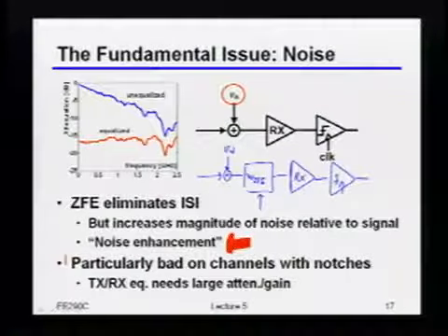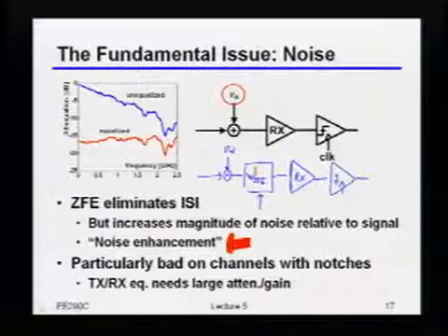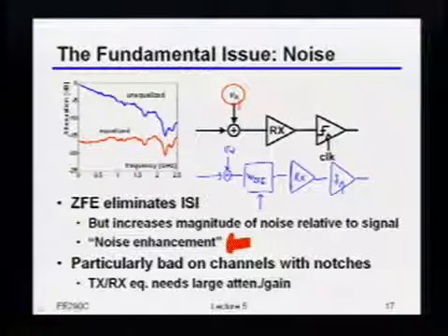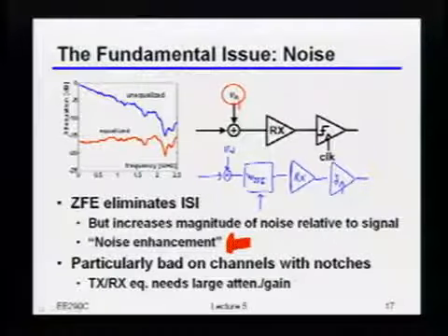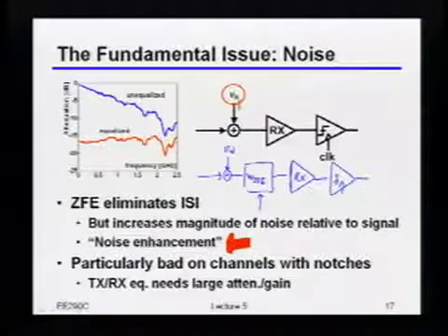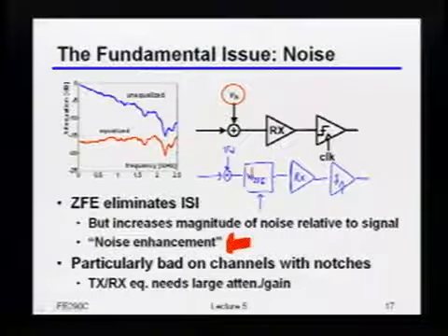Okay, so good. So you guys are circuits guys, so that's good. So usually when you talk to the comm people, they just sort of assume this is the fundamental thermal noise that's out there in the world of you transmitting a wireless signal. Okay, which, by the way, even here exists, because you've got a 50 ohm term at the end of your line, right? And that has some fundamental noise in it. So you're absolutely right that when you really build this, that's going to have its own noise contribution.